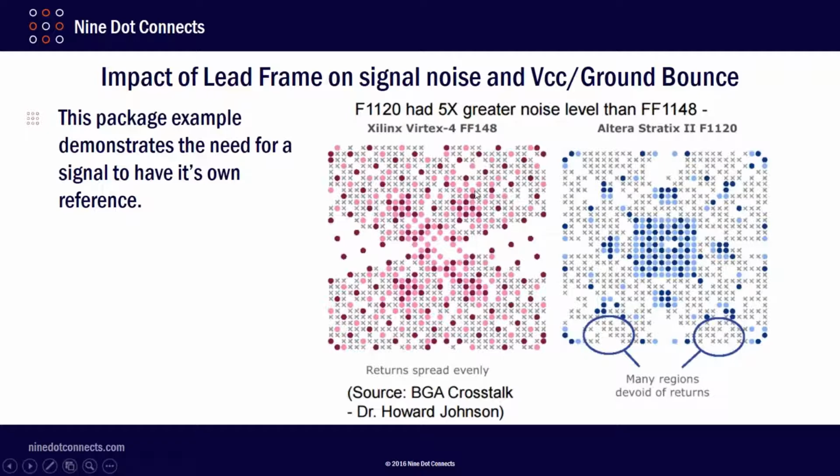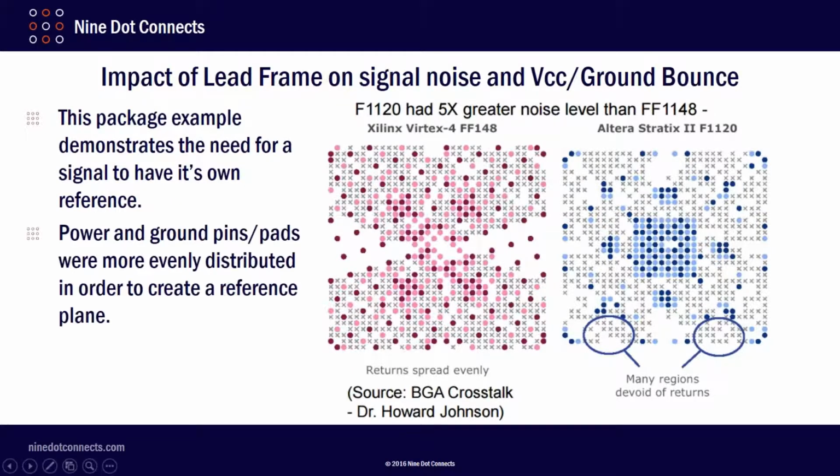Then if you notice, when the manufacturer said, well, we want to maintain signal integrity as the part leaves the die out to the board, then they dispersed the ground and power pins. So now it's not perfect, but it is much better. So they had all these IOs have a light pink or dark red ground power reference as their signal reference.